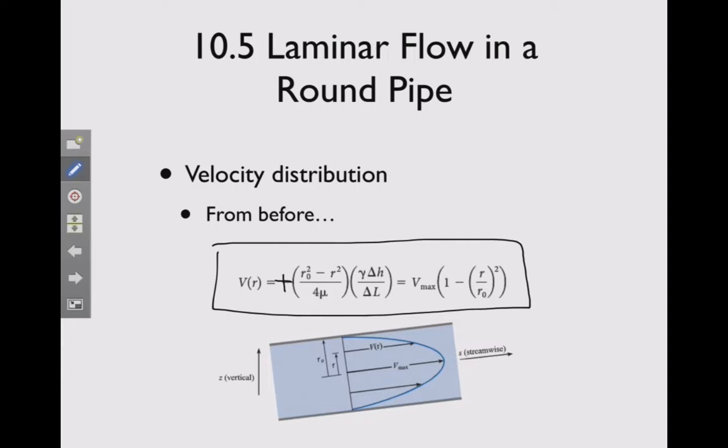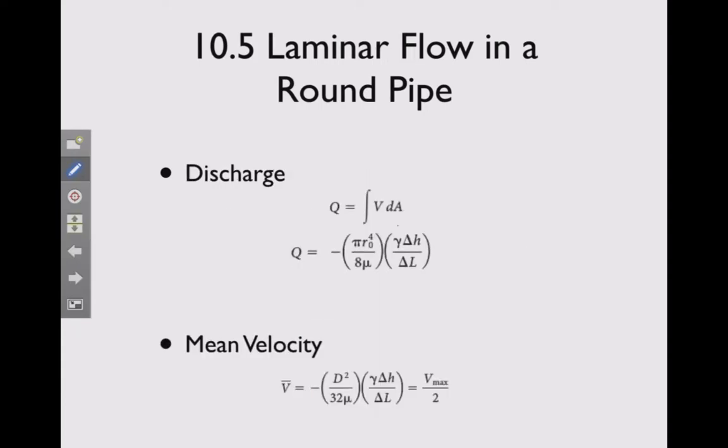I believe that's because they have switched their definition of what's positive and negative for the piezometric pressure. I'll show you that, and you can compare my derivation to the book's if you'd like. You'll see in my derivation these will also be plus signs, which I think they need to be. A positive mass flow rate and a positive average velocity makes a lot more sense to me.